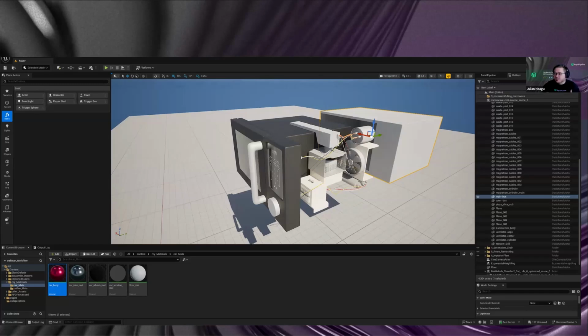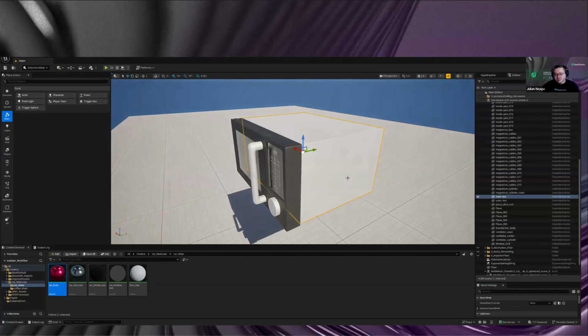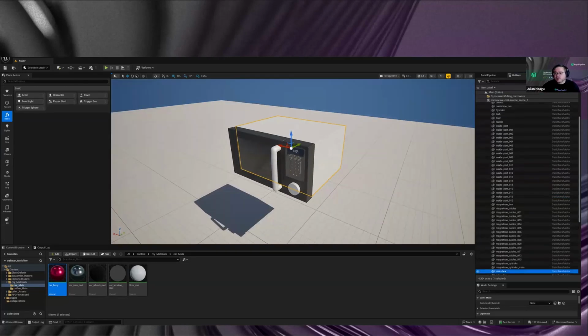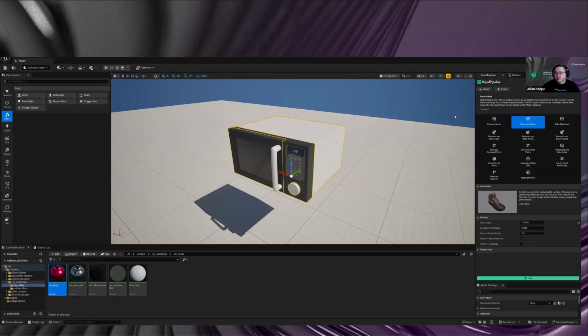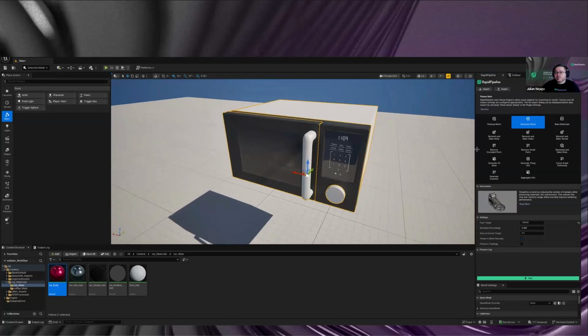And we don't have maybe time also towards that batch process topic to delete this manually or have kind of an occlusion object and put a collider in there or do the kind of culling process in more like an old school way, let's say. And instead, what we can do is we can just basically select the whole model, go in our actions and select the occlusion culling, remove occluded parts action.